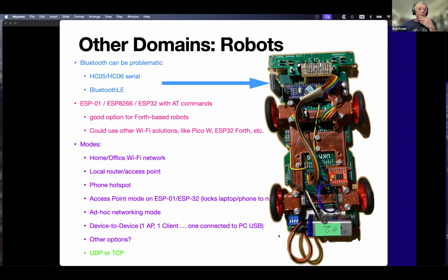So Bluetooth LE, as some of you know, is based on the same underlying encoding, but it's actually a totally different protocol, Bluetooth Low Energy, and it was designed for low energy sensors. Right, that was the original. So they've got effectively these attributes which are like shared variables, and you get notified when they change, and it's really designed for very low power sensor nodes. But obviously, specifically because they're supported on iOS or an iPhone, there's been a massive proliferation of these devices. So people like Nordic and others emulate a serial port using these attributes, right? It's probably the most efficient use of technology ever.